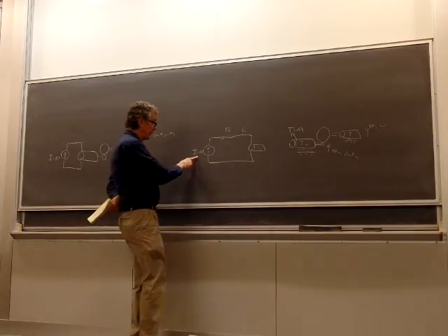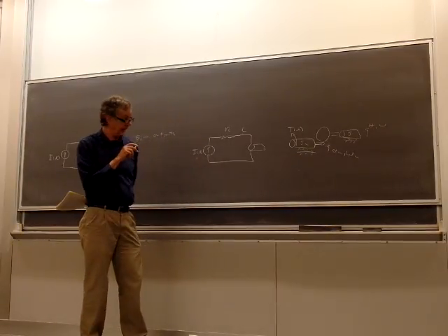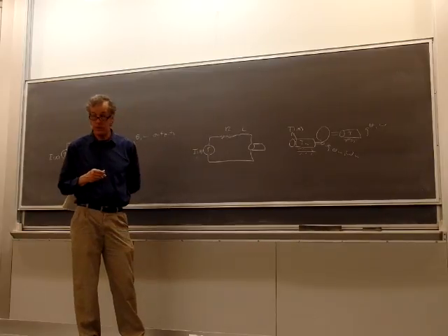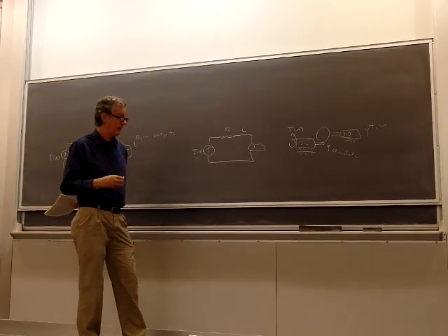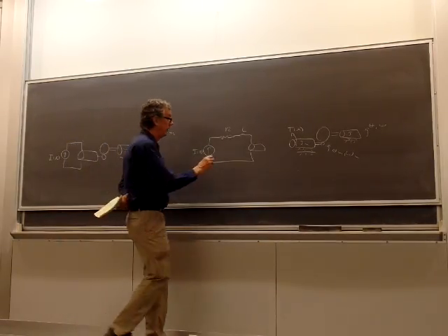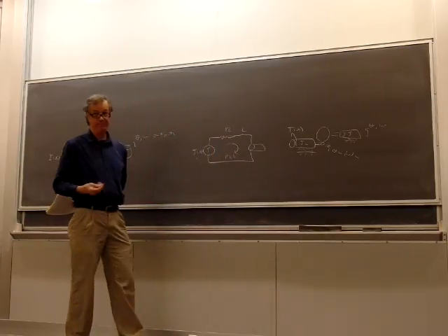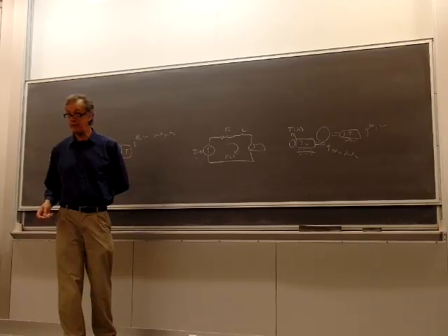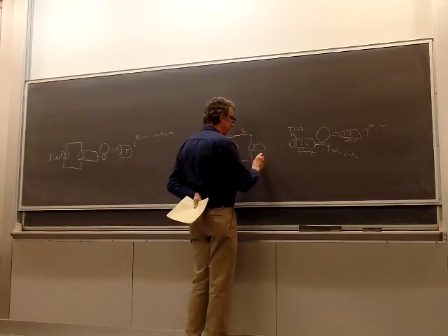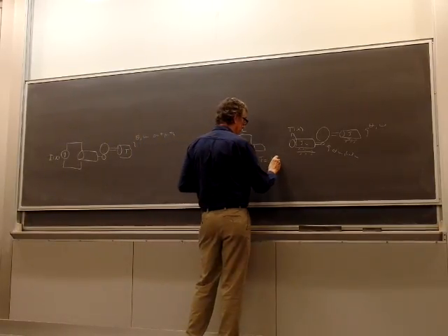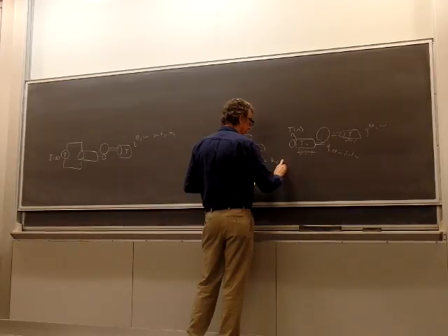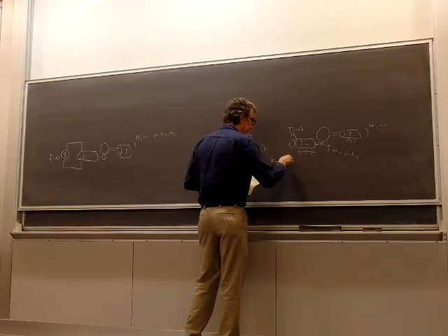Since this current source is on this, as you did in that one homework problem, it can supply whatever voltage is needed. So if you look at Kirchhoff's voltage law, it doesn't really give you any more information. It basically says that the applied torque is the torque constant times the input current.